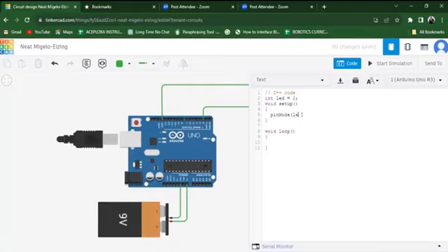So I'm going to be using LED, put a comma, right? And tell us what function it is carrying out. In capital letters, you write OUTPUT. Now, if this has been done, that's all. You've declared and initialized your LED as an output, right?